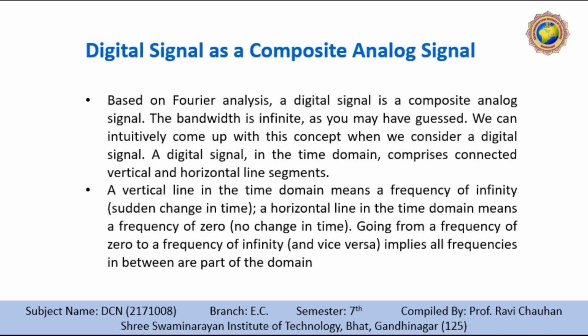The Fourier analysis can be used to decompose a digital signal. If the digital signal is periodic, which is rare in data communication, the decomposed signal has a frequency domain representation with an infinite bandwidth and discrete frequencies. If the digital signal is non-periodic, then the decomposed signal still has an infinite bandwidth, but the frequencies are continuous.